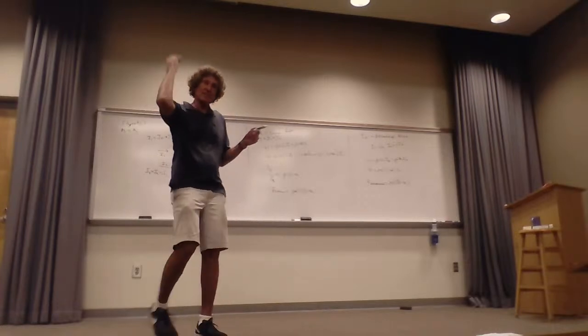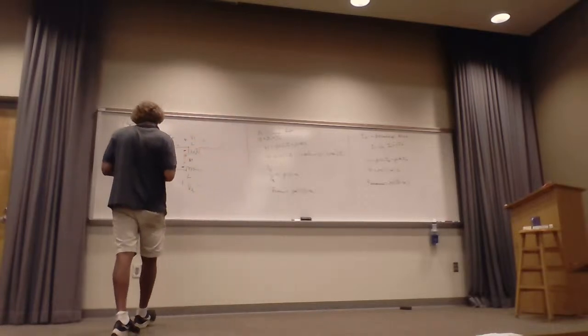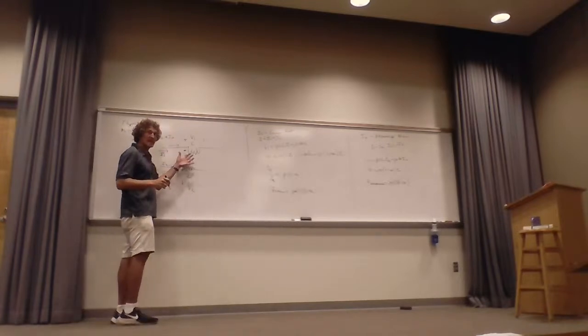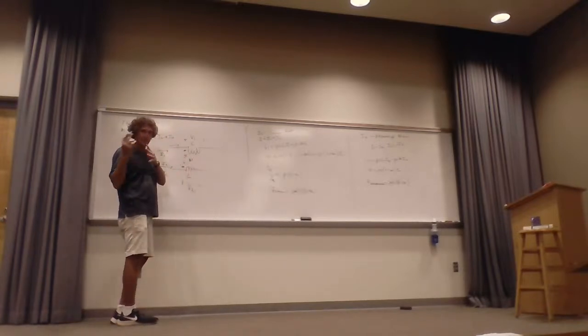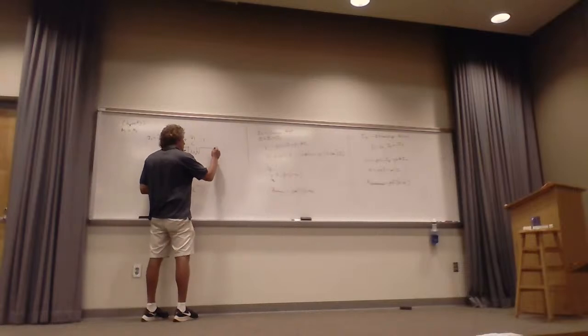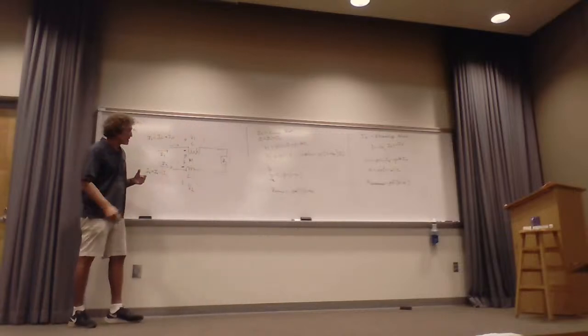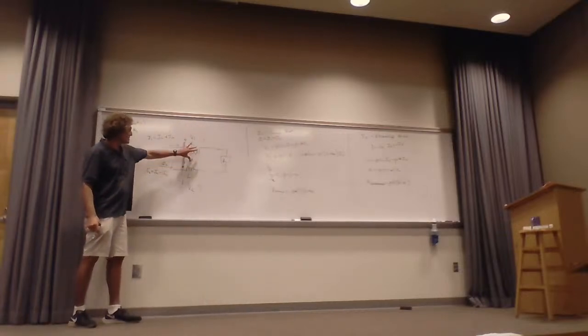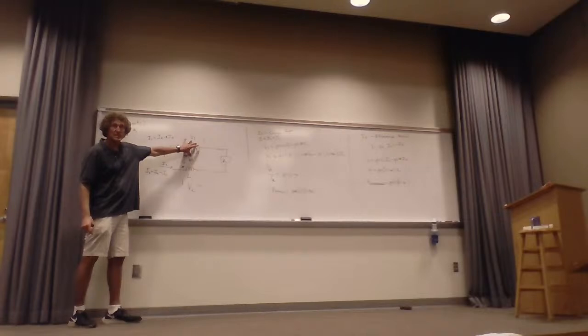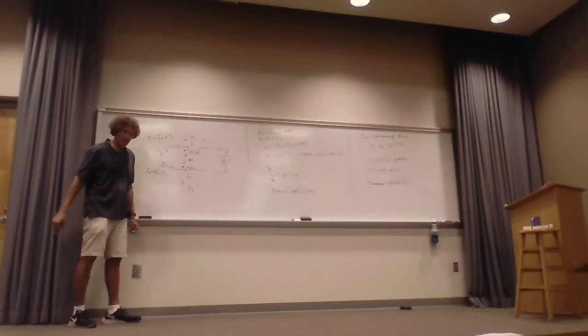So if you wanted to see the effect on the differential mode, if I put this in here, and I gave you M, gave you L, gave you the frequency, and then you put in a load here, some ZL, the only thing you would do is you could replace both of these with 1 and just put in J times 2 omega L minus M if it's differential, or J omega L plus M if it's common. Y'all follow me?